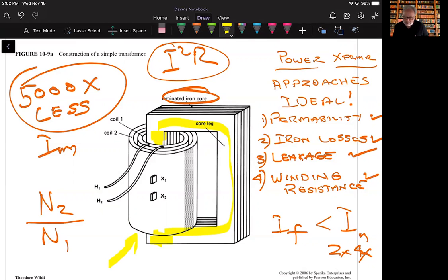In larger transformers, the cross section of the laminated core is not square, but is built up to be round. The squareness is not conducive to coupling of the flux. That's why we see round transformers. A good example is the top of a power pole, where we see a round transformer. If you look at a model train application, those transformers are square, but there efficiency and power are less of a factor.